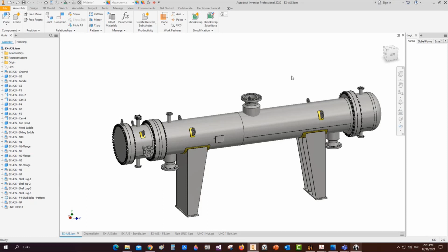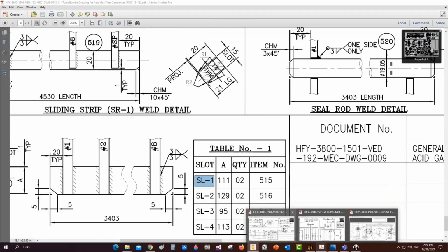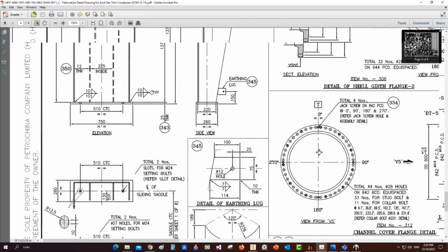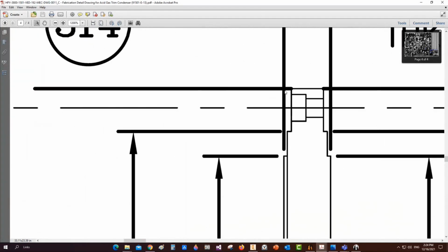If you refer to our drawings, in the bundle drawings, you can see counterbore on the tube sheet hole, not on all the bolts, some of the bolts. Counterbore, yeah. You prepare the counterbore holes, but this stud is a different type. It's a collar bolt, so we can't see that configuration here. This collar is an integral part of the bolt. Can you open our bundle drawing? I think you are talking about this hole. Is that right? Yeah. Okay.